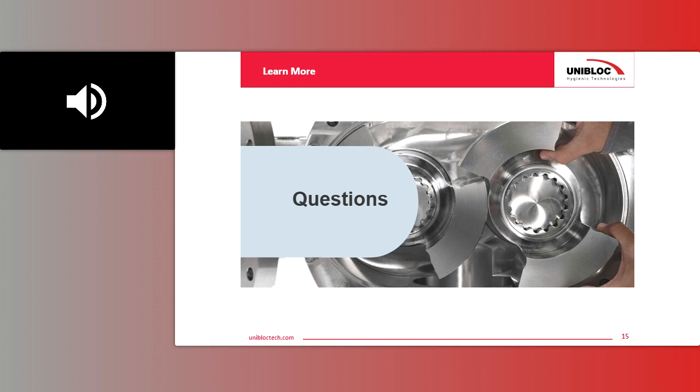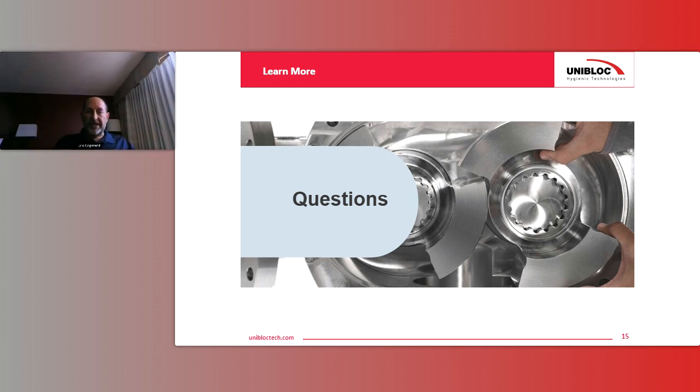Is there a downside if the pump deadheads? It depends on the technology. For most pump technologies, if you deadhead the pump, yes, there is a downside. PD pumps are positive displacement. If something deadheads, most pump technologies will keep building pressure until something gives or something breaks. So yes, the downside is something can break downstream.